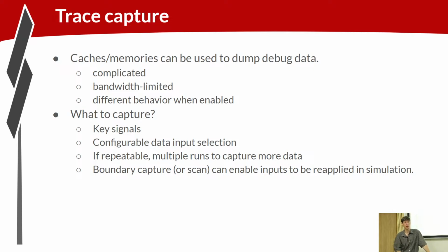That is only if you can do this repeatably, right? It's also important to capture boundaries, all the input data going into a block of logic, so that you can reapply those inputs, right? So if you can capture all the state of some unit of logic, some boundary of logic, and you can capture the input values going into it over time, you can set up the initial state and reapply all the inputs and regenerate that in simulation.